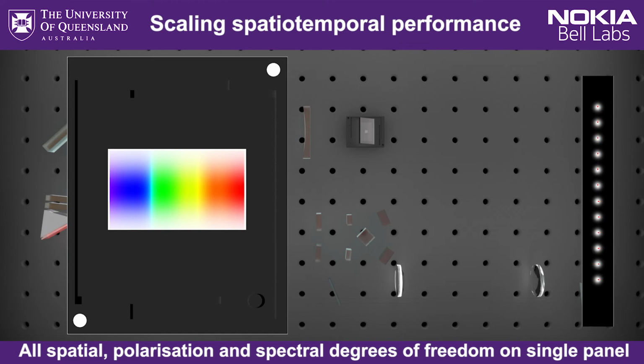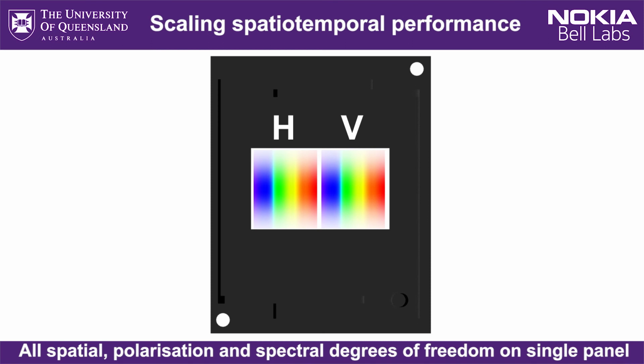It could potentially be a lower loss, as the overall polarization splitting is programmable now. Downside is you're asking more of the spatial resolution of the SLM in that Y direction. So in this case, we went with the more conservative route of splitting the SLM horizontally, which trades off some resolution in the spectral dimension to effectively gain some in the spatial dimension. For the first demo, we were more interested in making sure we got all the spatial components rather than tweaking things like loss and that kind of stuff.